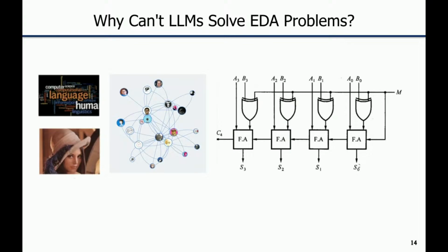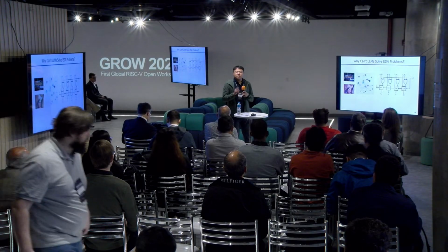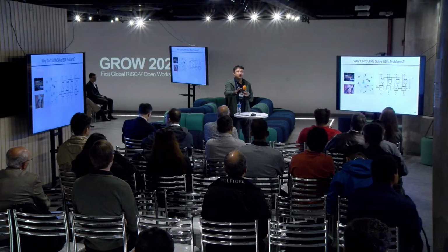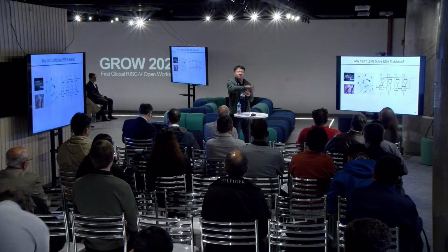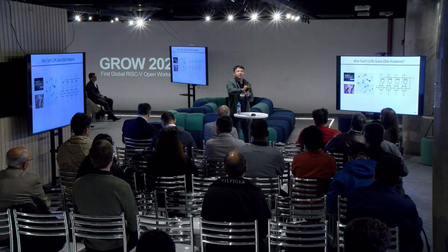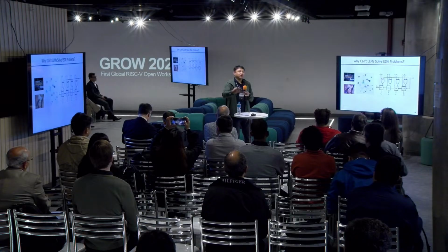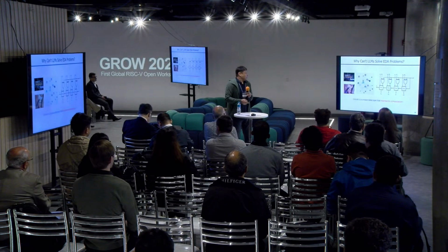One reason is learning. First of all, learning is about first representing the data. I need to represent it in the vector space, and then I can do all sorts of computations on top of it, right? Compared to text or image, what's unique about circuit is that for text and image, all the information you want to learn actually exists in the raw data. All the information is out there. A circuit essentially conducts computation. If you don't run simulation, you don't know what the output is for a given input. The data, sitting there, doesn't contain the information, so you have to do the simulation or other things yourself. That's a key difference.